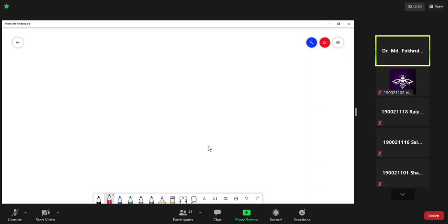If we summarize the advantage of the active filter, we can say that the maximum gain, or the maximum value of the transfer function, can be greater than unity, and the loading effect is minimal, which means that compared to the passive filter, we can eliminate the loading effect.